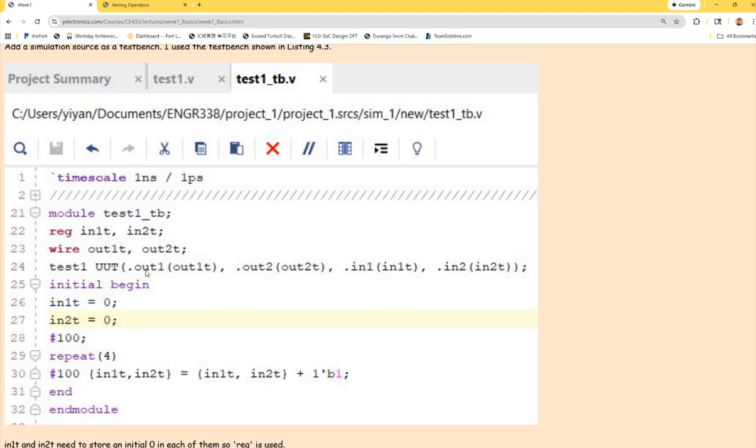We probably have to do the quiz next time, but let's try to finish it in class as much as we can. So now I'm going to give you time. Looking at the schematic of the half adder, use 3 different modeling methods and the correct port names indicated in problem number 6 to form the half adder in Verilog.